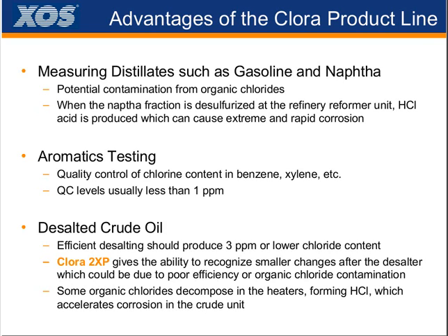When that naphtha fraction is desulfurized at the reformer, that hydrochloric acid, which we talked about earlier, can crop up, and it can cause extreme and rapid corrosion. Like we said, high pressure, high temperature situations, you could run into issues there.